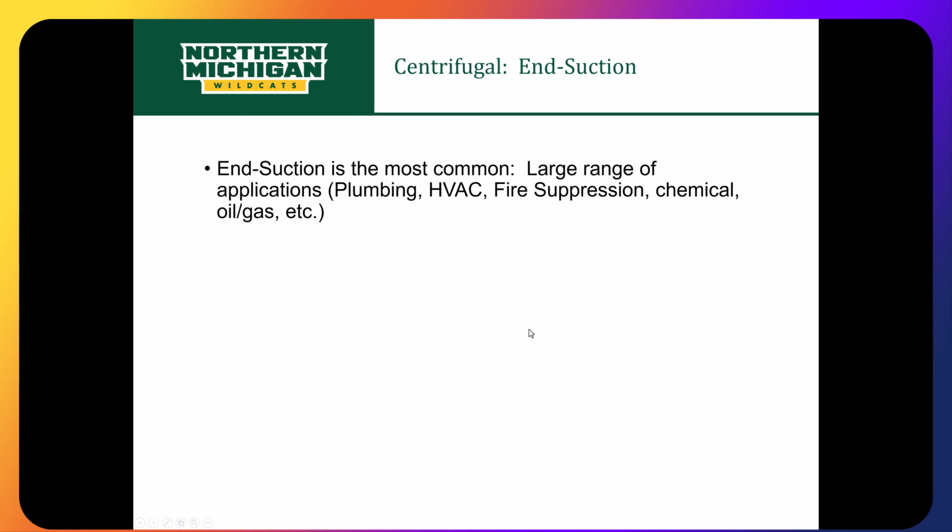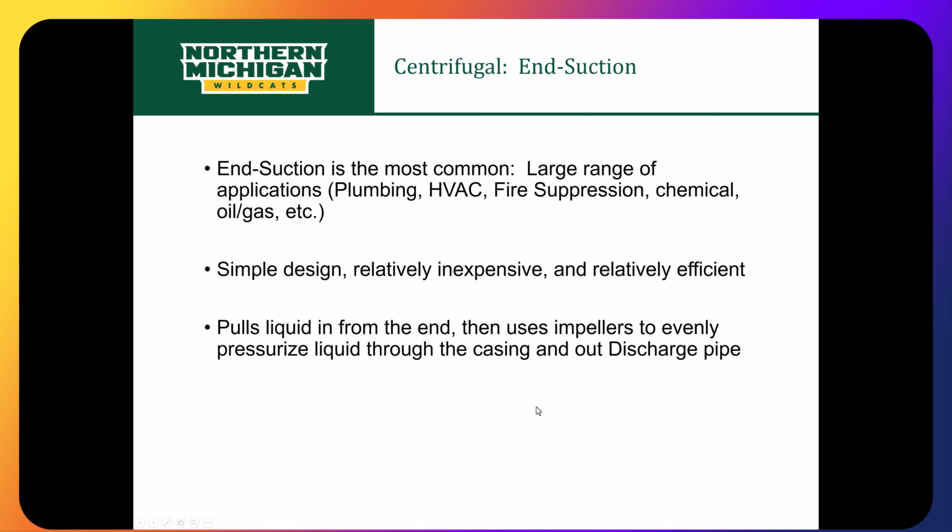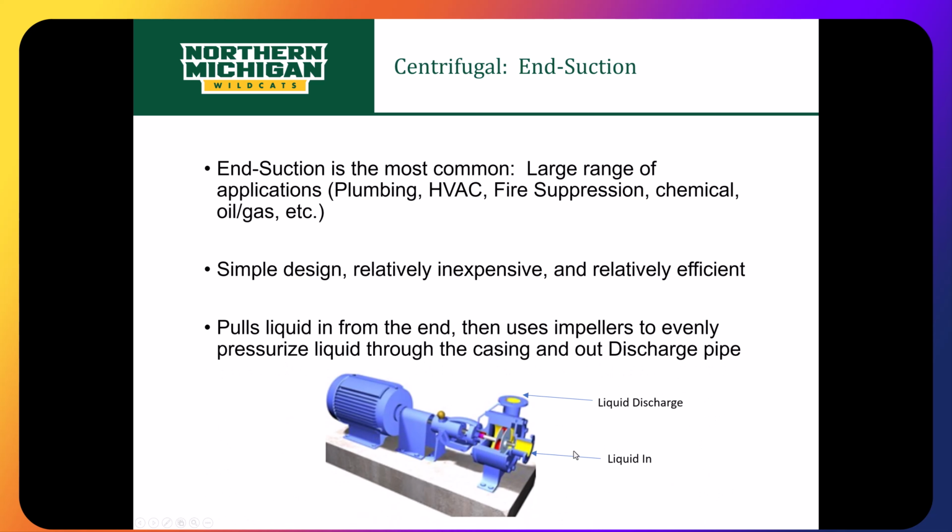So again, your end suction is the most common. It's a large range of applications. We use it for a lot of different things. You'll see them all over your building for different reasons, or multiple different types of buildings, I should say. Very simple design, relatively inexpensive, relatively efficient. And it's pulling that liquid from one end, liquid coming in to displace it and discharge it all throughout your facility.